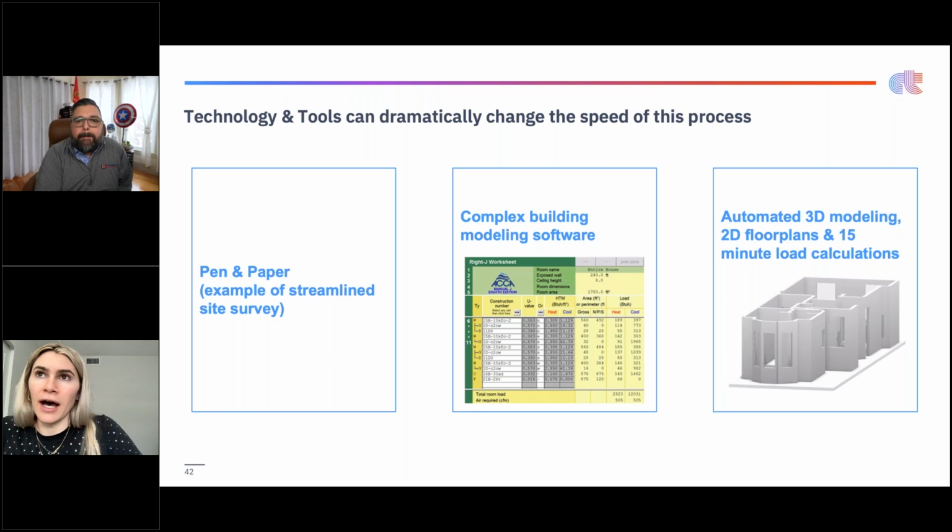And so this is where we started using LiDAR imaging to scan homes, build out 3D models, build out floor plans, and then automate the load calculation process. So it's a question of what you are observing in the home, starting with property data, but what are you observing on top of that that you might want to change, and then combining that with a user-generated floor plan and 3D model that adequately takes into account a lot of the important factors that Chris mentioned. So size of windows, the direction and orientation of that space, whether there are overhangs or not. A lot of that we can see directly just by scanning the home and building out that model.